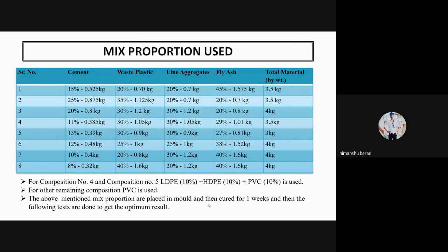And then we do casting and other processes. We generally cure our bricks for 1 week, since we have to perform multiple trials and we can't wait for 1 month total strength. So we only perform it for 1 week strength.